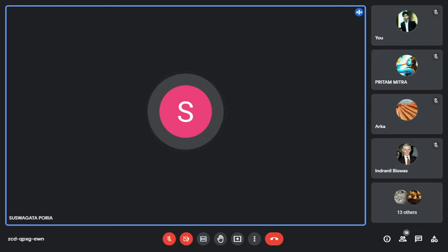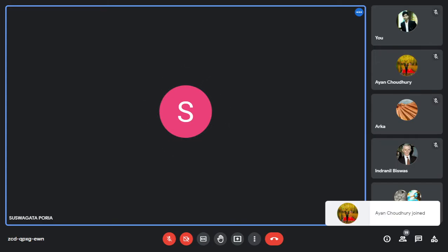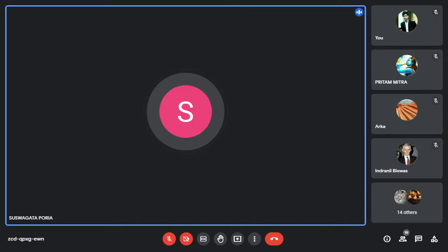Fourth thing which I have seen, that is, some of you have not put the center line properly in the drawing. That's a big mistake, because if you don't give center line, then the meaning of the drawing will be changed. And you also know that if you don't put a center line in a rectangular hole, then the meaning of that hole will be a rectangle. That will not be a circle.